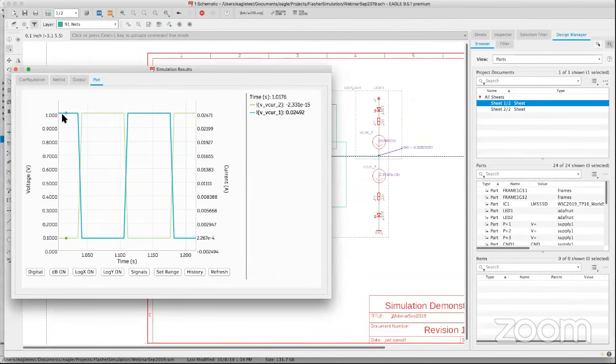So as you can see, when it's on the screen where I have it right now, you could look at the values right here on the ammeters. That way you could see at which portion this LED is on or off as well. When you see minus 15th power amps, that means it's off. And when you see it on, it gives you 0.024, almost 0.025 amps. Okay.